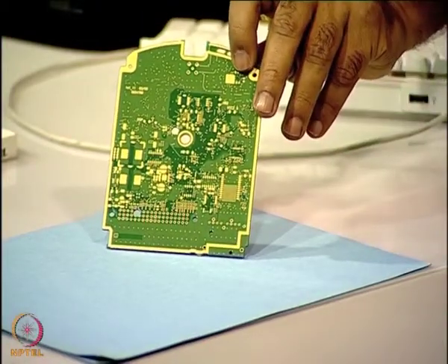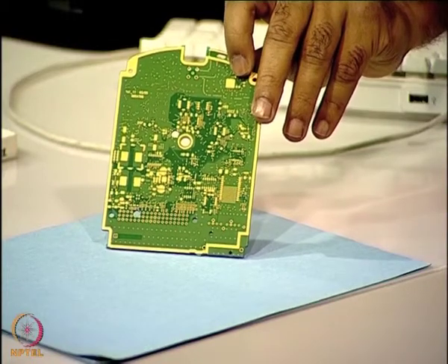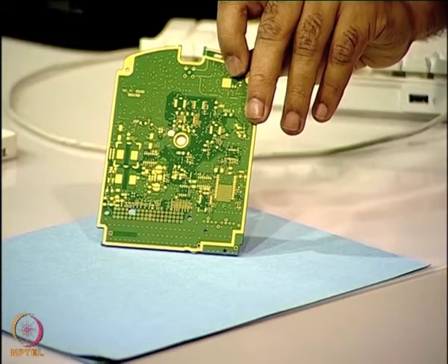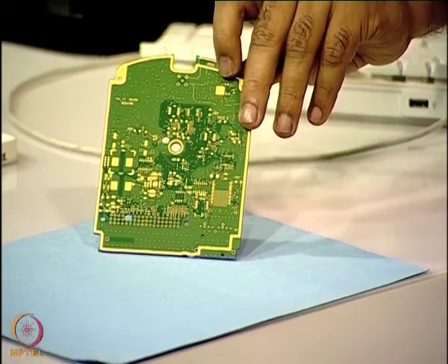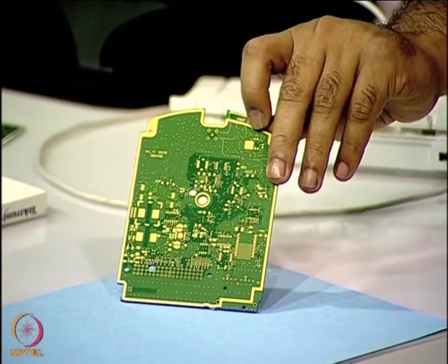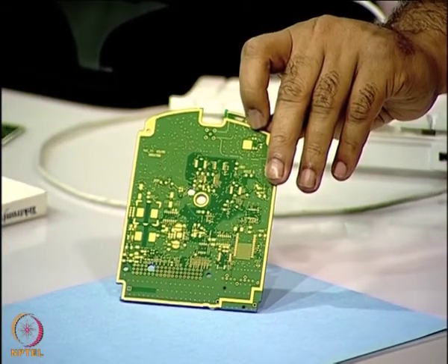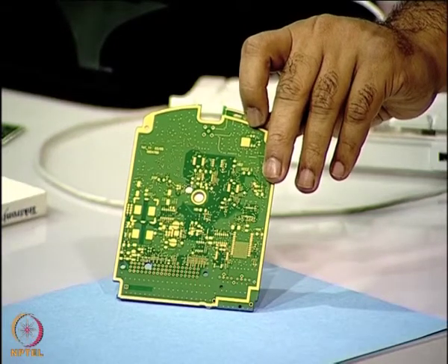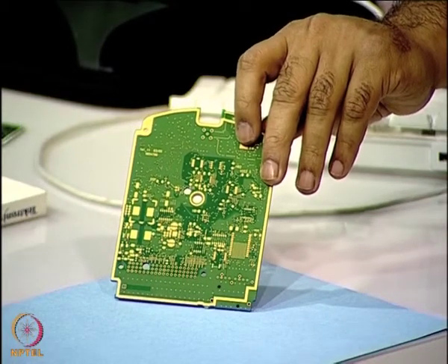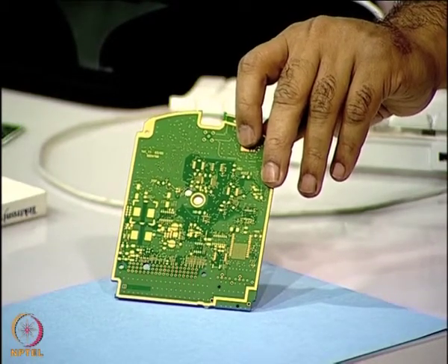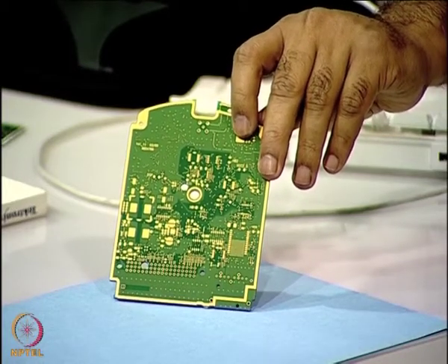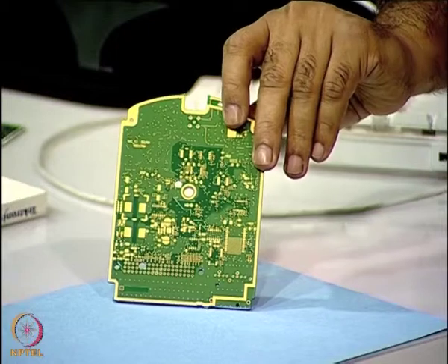This is a gold plated printed wiring board, and in fact, if you look at it very closely, this has got mechanically drilled through holes of the order of 0.15 mm, that is 150 microns, and these through holes have been made electrically conductive. That means, they have been plated through hole in these PCBs and they are highly reliable. So, these are used for specific applications.